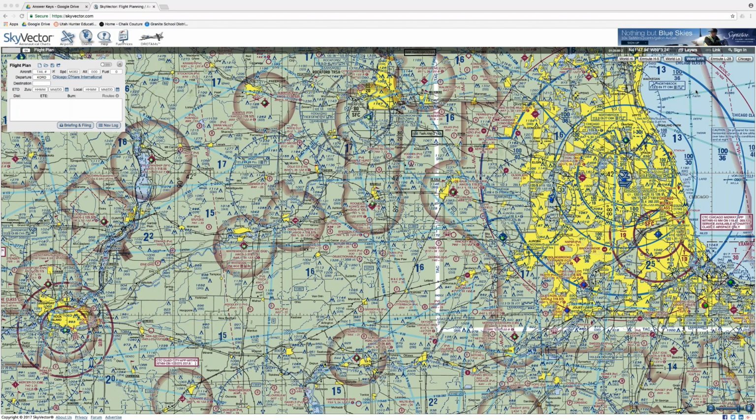According to the FARs, how long can a dispatcher be scheduled for duty in a 24-hour period? 10 hours. Perfect. All right. According to the FARs, what 3 things is the dispatcher and PIC jointly responsible for? So what are the 3 things that we share responsibility for with the PIC? I want to say the PPDD. Pre-flight planning, delay, and dispatcher release. Yep. Perfect.